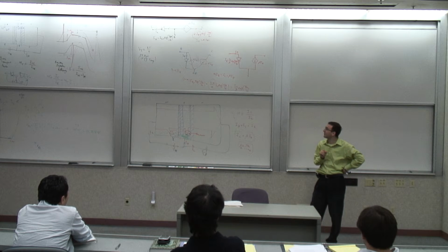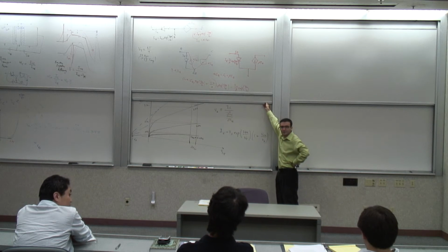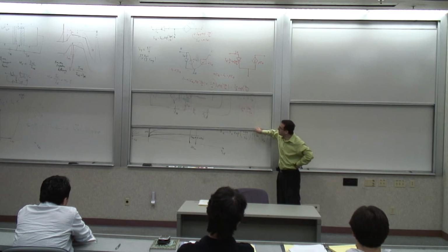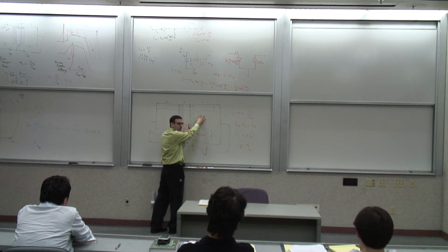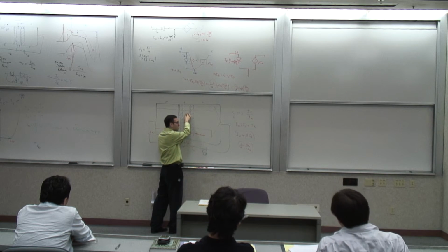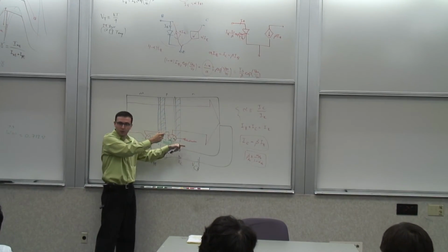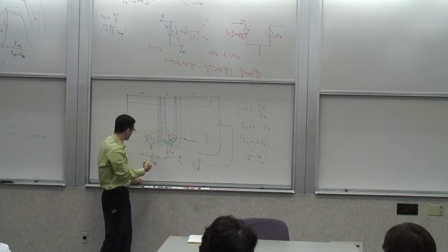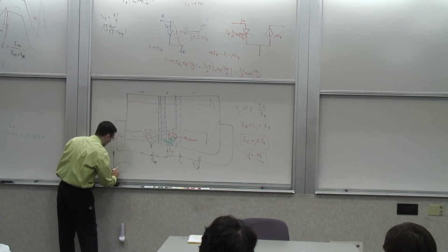What we just talked about. The current variation with VBC. Yeah, the early effect. Because now, again, I have a very bad situation because this side is more highly doped than the base, so most of my depletion region falls on the base side. A slight change in this voltage results in a major change in the base width. So my curves for IC versus VCE, instead of looking like this, well, they look like that, they now look like this.